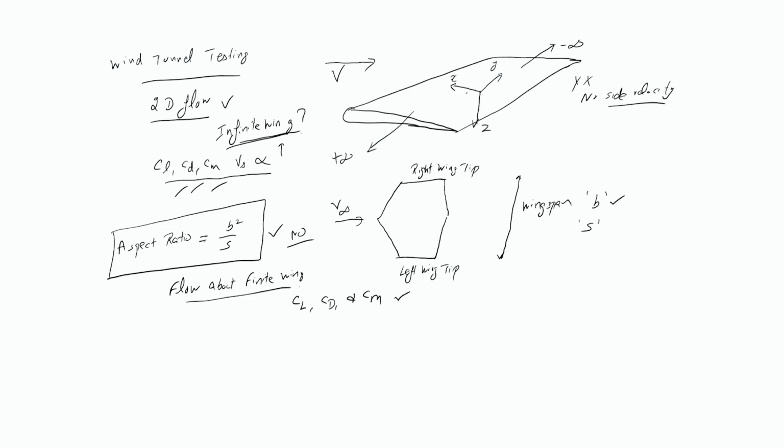I often ask this question to students. So if you consider a NACA 2412 airfoil, and if I tell you to do a wind tunnel experiment at alpha equals say 6 degrees, and you did the whole hard work and finally found the plots of CL versus alpha curve, what you got was CL equals 0.85 and CD equals 0.077.